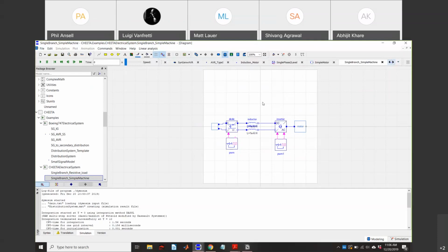No, that depends. No, sorry. That is entirely dependent on the control hierarchy that we want to make. So typically, in this kind of system, you have a two-layer, or even 3-layer, control hierarchy. The 3-layer control hierarchy starts at your flight controls, then it goes to the energy management system, and then the energy management system sets the reference points for the distributed controllers at each of the devices.